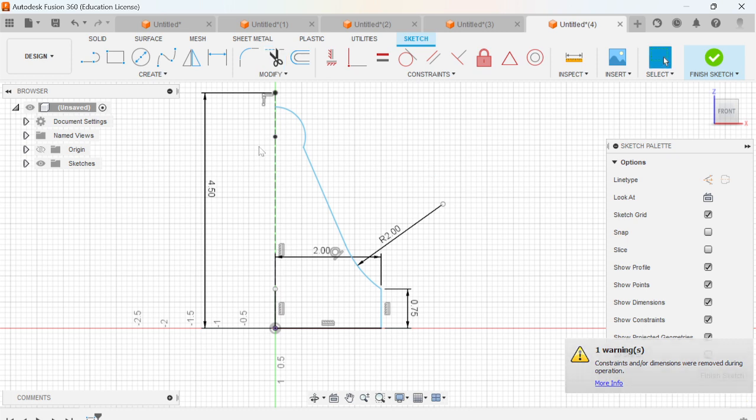And you'll notice everything here is still white. I'm gonna make another line and connect this. It turns blue, right? So you can only extrude solid shapes. Control Z, it's white. This is not a closed shape. We're missing a line over here.